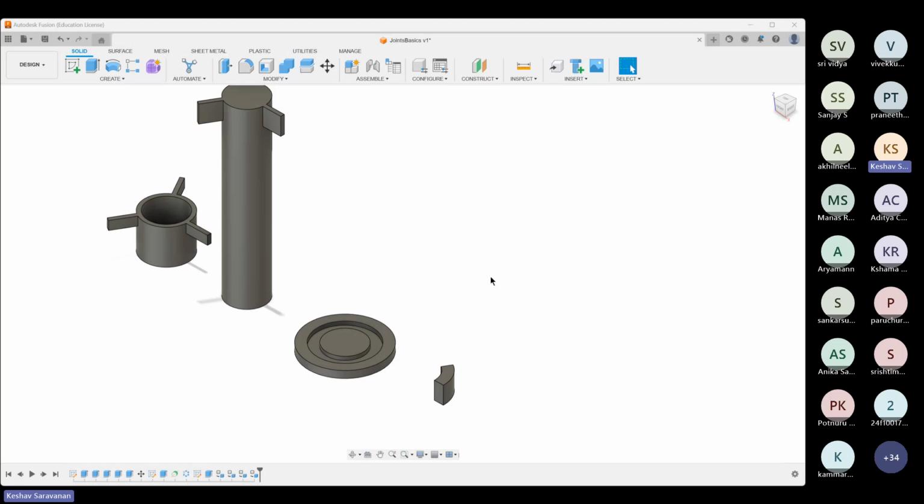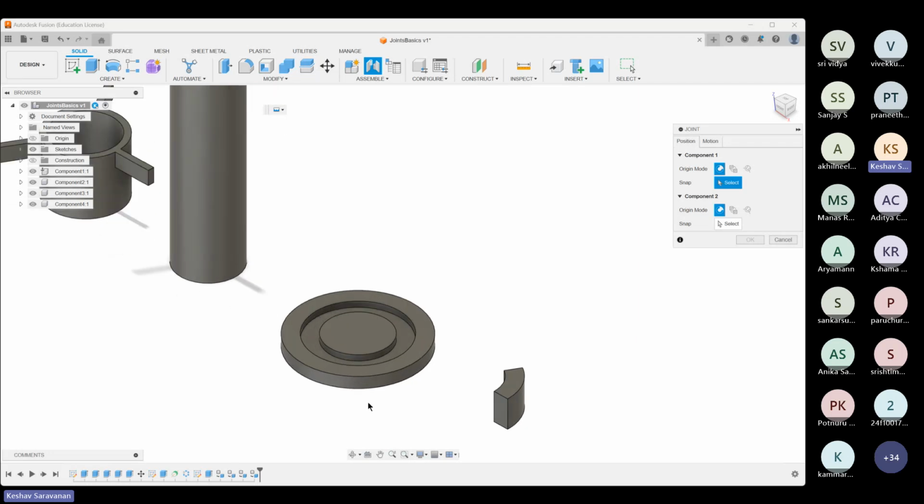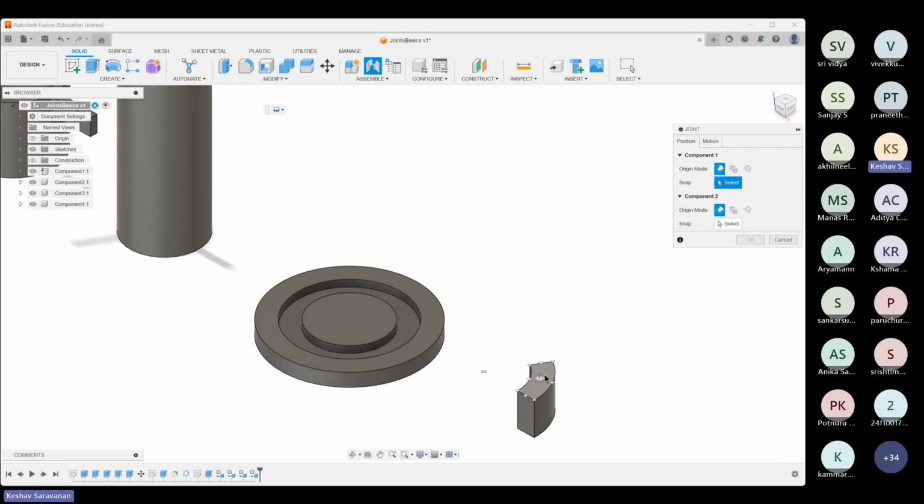Two in the second part. Okay. Oh, okay. You wanted me to show you that Control thing. Okay. So right now I want to choose the point I want to make the center of this arc overlap with the center of this circle over here. But the problem over here is the center does not lie on the body. So if I take my mouse out of the body, that point will disappear. So what I do is I place my mouse on the body, I wait for that to highlight, and then I hit Control. I hold Control down.